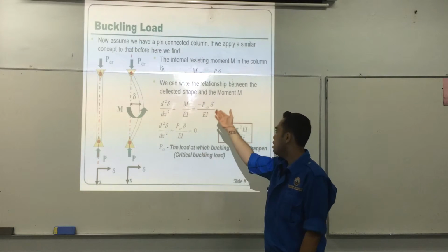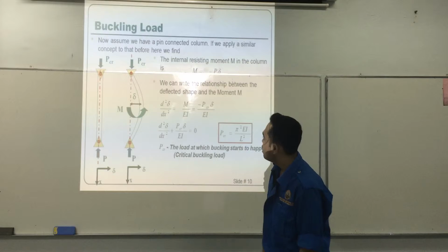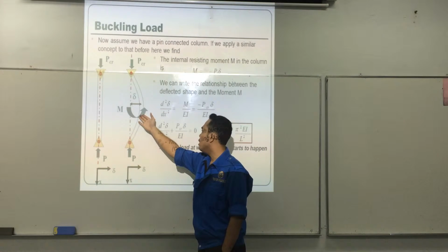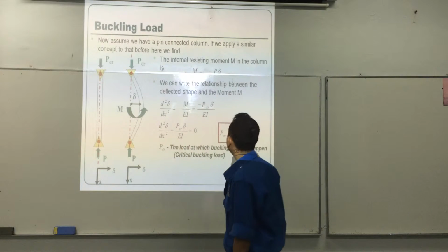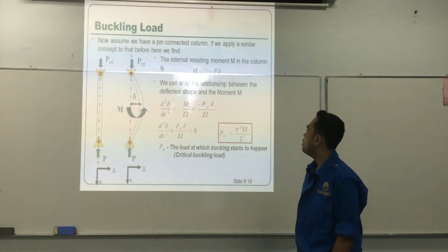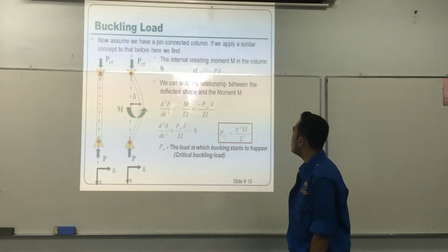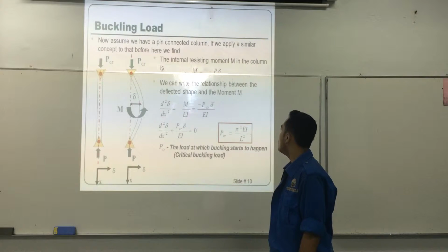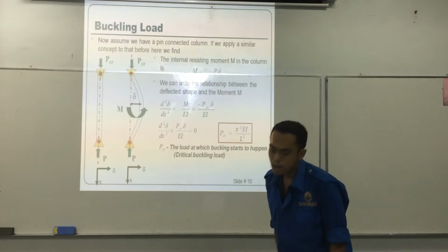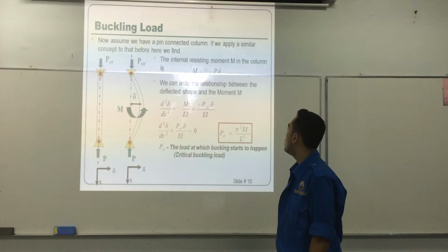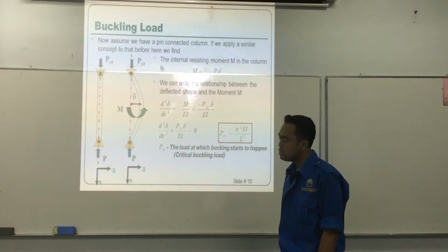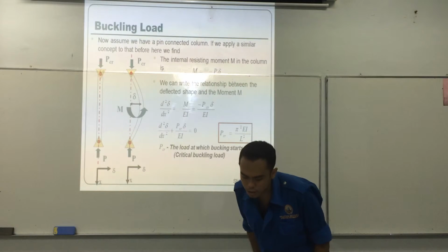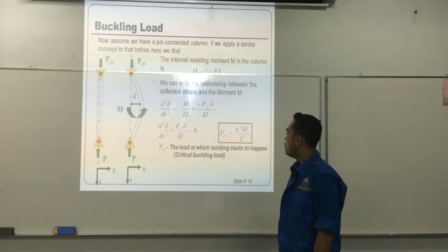This is the buckling shape. The load that we have applied gives us bending like this. So we have a formula to find the critical load. M equals minus P times the deformation, where M is the moment, P is the force, and the deformation is the deflection.